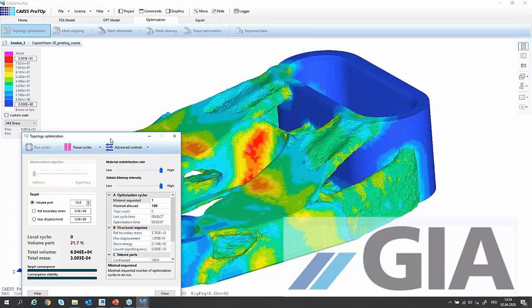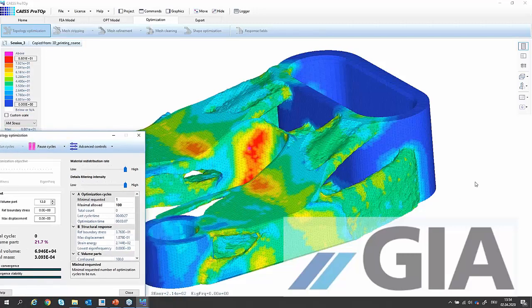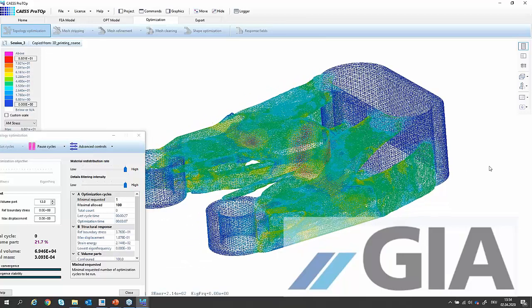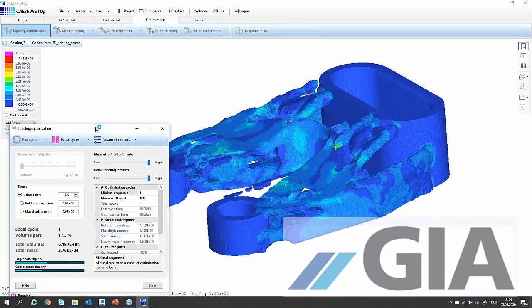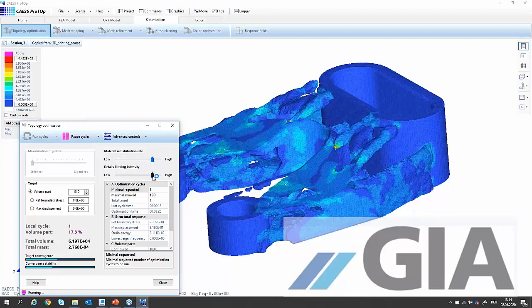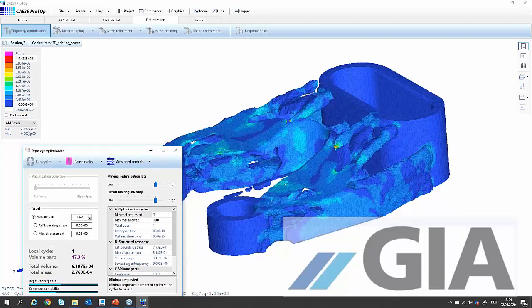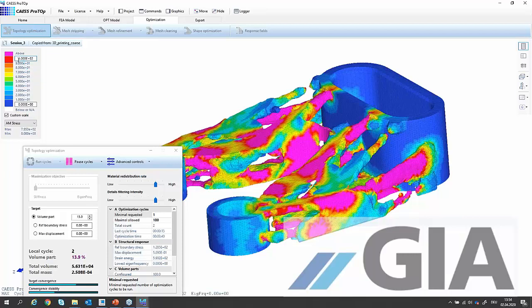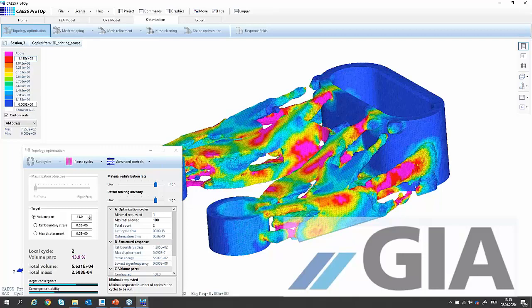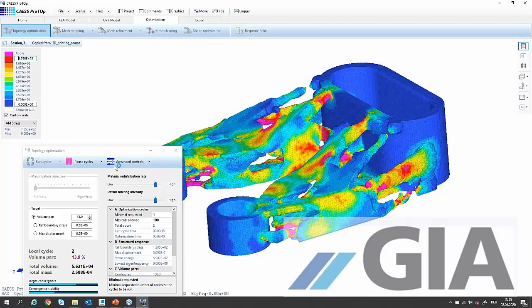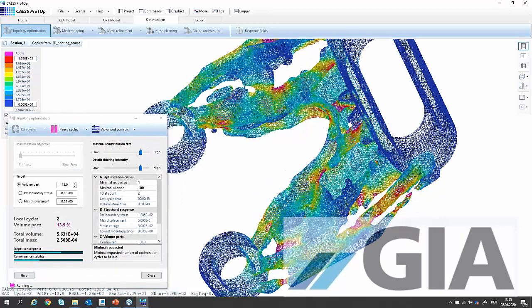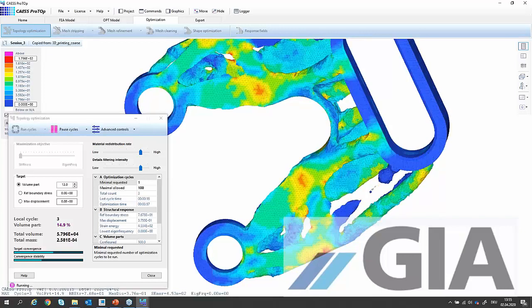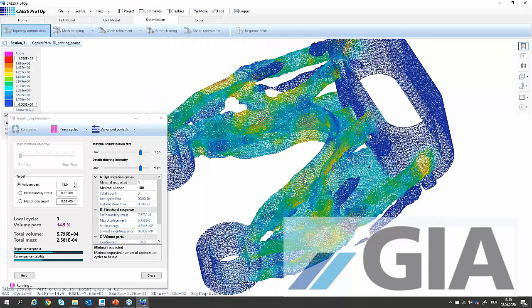And we see right now the stresses, and now about every 25 seconds another cut will be done. I'm cutting away quite aggressively right now. Let's do it a little bit smoother here. I'm using my custom scale to have stresses between 0 and 100 megapascal. Let's go a little bit up here. You can also use the mouse wheel to do that. Okay. So you see right now I was in between. I was a little bit very aggressive, so it cut away this bar here, but that doesn't matter.